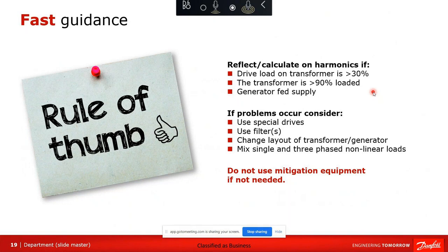I would not. I would run it through the analysis and see what filtration systems I need to add, or what mitigation systems I could add that gets a transformer loading down to about 80%. That's going to just guarantee the best performance. Okay. Well, you know, 55/65 degree means that's 2 ratings. So you got like extra 15% capacity if we go to the 65-degree rating. Obviously, there's more heat generated in the transformer, which there's more losses.